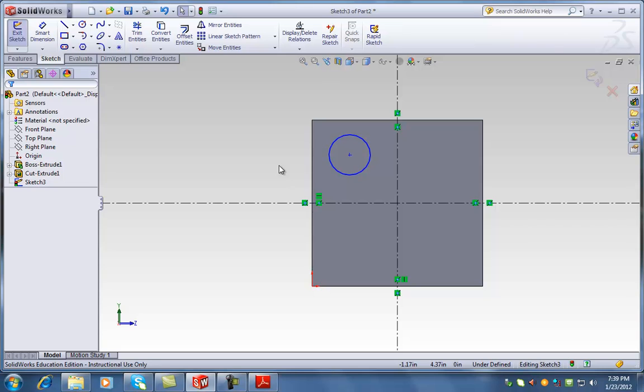Okay? Now, we talked about relations last time briefly, but I want to emphasize the idea of relations. Relations are something that you try to do in order to connect two things together. Now, there's different types of relations. For example, if you select 2 points, some of the relations that could be is coincident. But if you select a point and a line, now I have more options. I could be coincident. I could have the point be at midpoint. I can do all these different things.